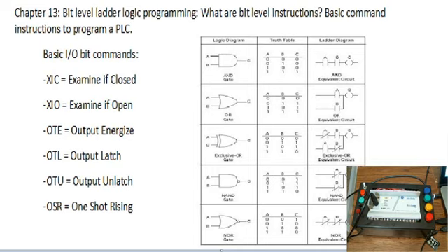In this lesson, we are looking at bit level ladder logic programming instructions. These are some of the most useful commands that you could possibly use in ladder logic programming. They include, but are not limited to, the XIC, examine if closed, XIO, examine if open, OTE, output energize, OTL, output latch, OTU, output unlatch, and OSR, one-shot rising.